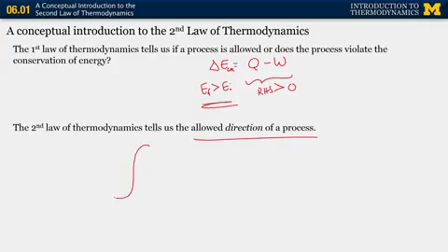So you can think of all sorts of good thought exercises. You could imagine, take for example, the change in potential energy associated with a hydraulic power plant. So let's take a dam and we're looking at the energy generation. We can set up, again, a conservation equation for this system, and we can make it a control volume or control mass on a rate basis or whatever is appropriate. And we can, in fact, check the box that the criteria for the conservation of energy is met. But we can't tell from this analysis whether or not the water should be going down or should be going up. And again, intuitively, we know the water has to go down.